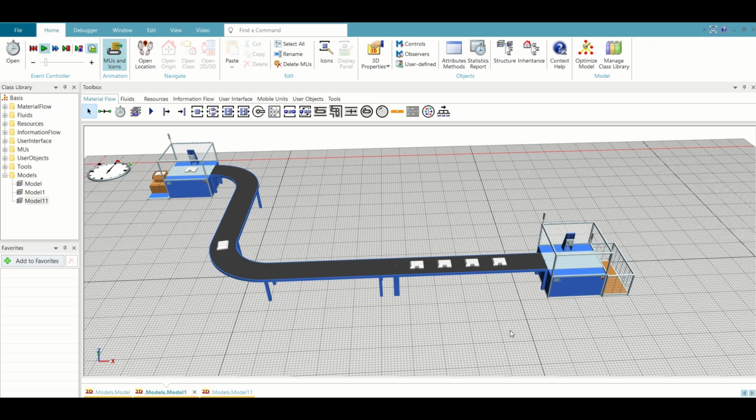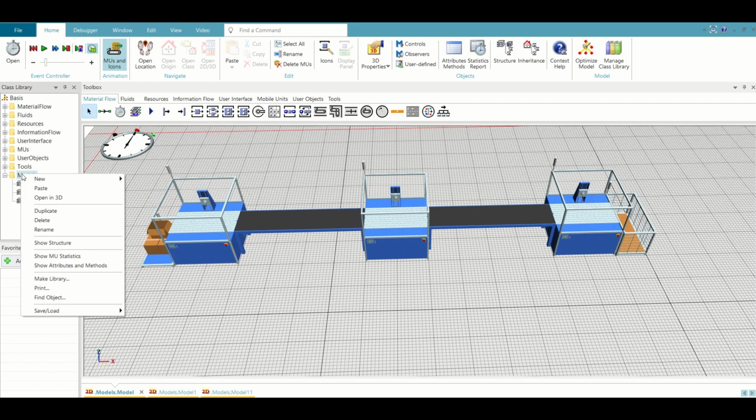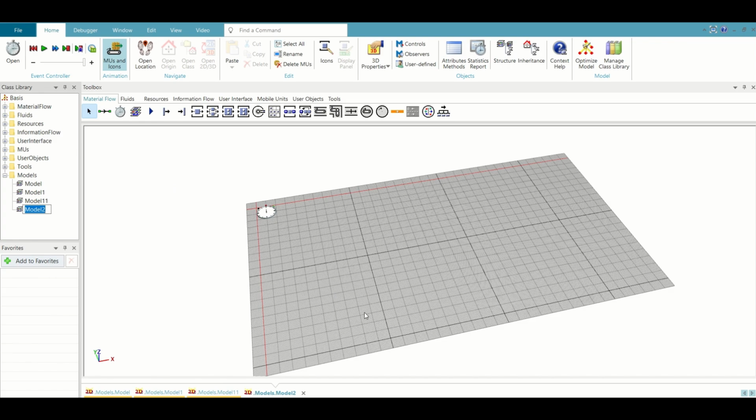like that. Now we are going to create a new model in this simulation environment where we will understand how to create cross conveyors, okay, merging conveyors. Now let us go to that exercise. I'll reset this and let us right click on this and create a new model frame. We have a new model frame here.